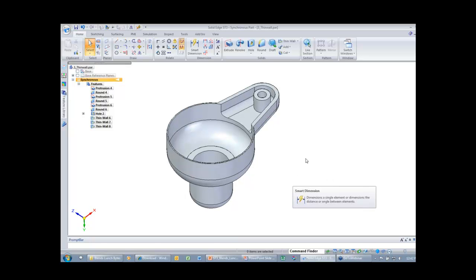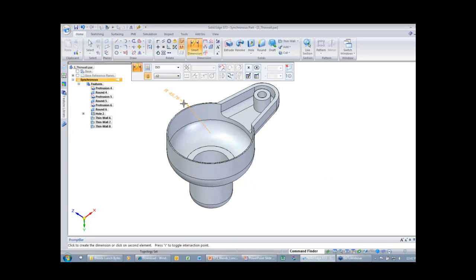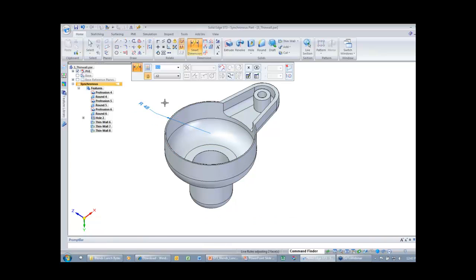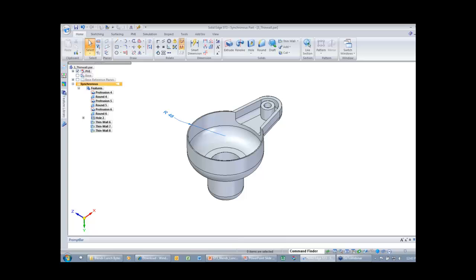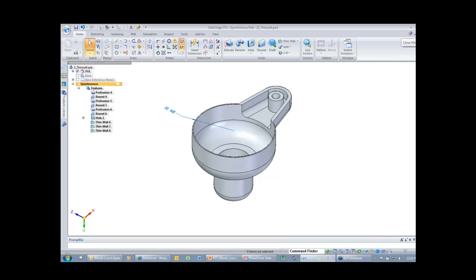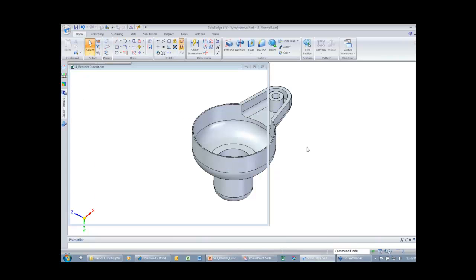With the synchronous idea, if you've looked at anything synchronous, you know that we add 3D PMI dimensions directly to the model and make a change. Notice if I do a smart dimension to that inside face and make a change, obviously it's going to maintain that thickness because it knows that that thin wall exists. So it's going to push out that thickness because of the thin wall. That's a little different workflow for us to get different thicknesses, or what we call a unique thickness, inside of the ordered environment, where you also have to do more of a thin region concept. So I wanted to take a little bit of time to show you that because that is a little different.